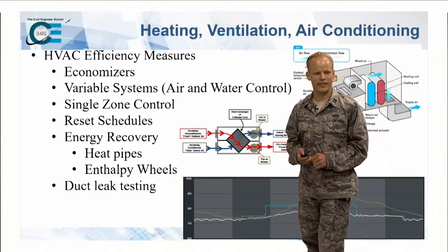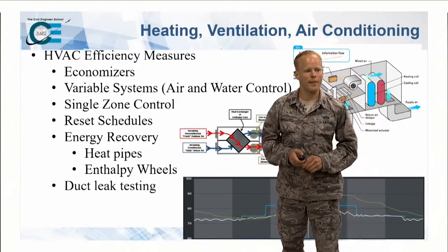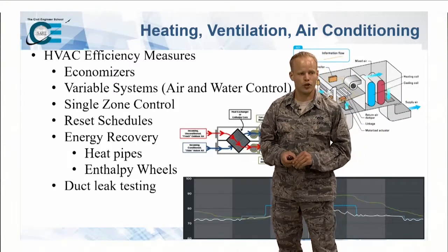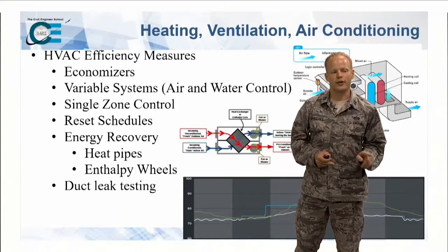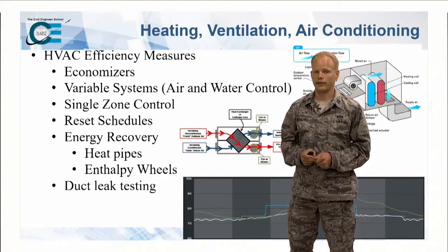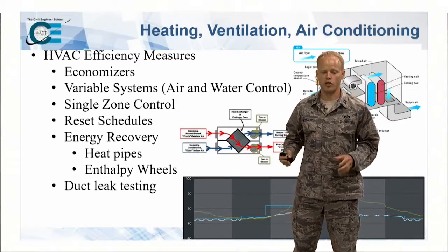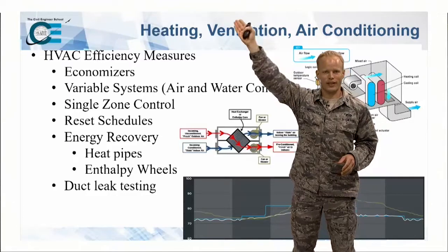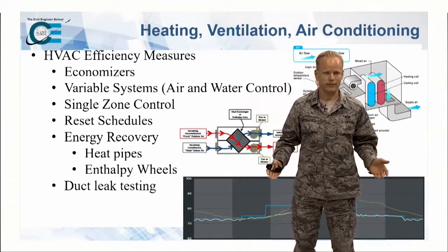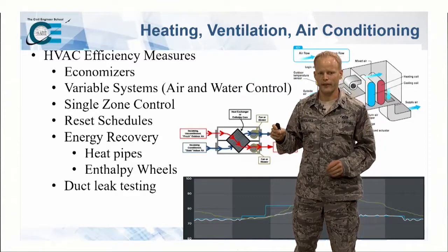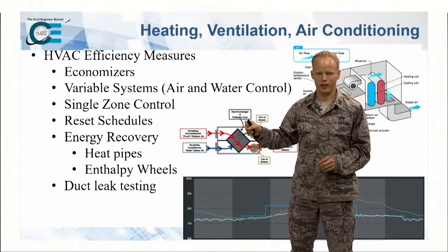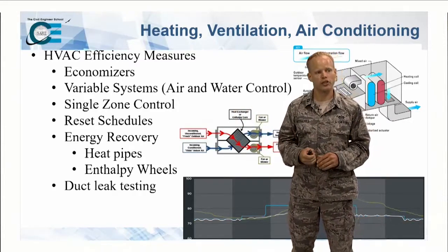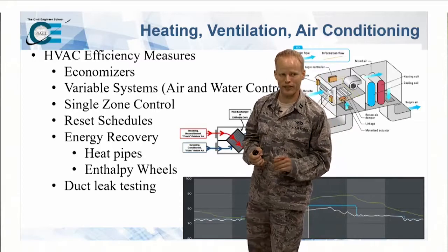And then duct leak testing. So I see the comment on there, better circulation will provide better cooling without air conditioning. Okay, that's true. I saw better circulation, so I'm going to touch on that point. So if you have duct leak testing, making sure all the air is going where it's supposed to. If you have conditioned air leaking in your ceiling, above the ceiling, you're just wasting air. It's like leaving a drip on your faucet. That's just water you're not using. So if you can get it all going to where you need it to be, better. Better circulation will provide better cooling without air conditioning, as said there.